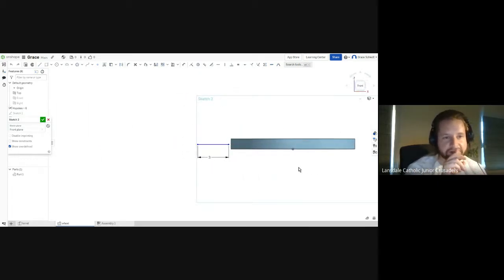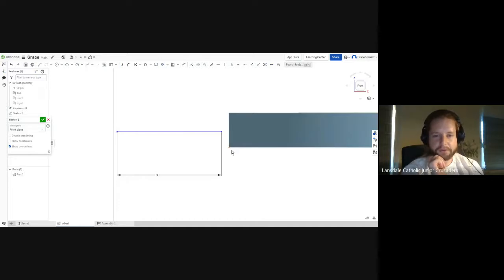So do you see how your sketch one isn't visible right now over in the left? Yeah. Yeah, click that. There you go. Now you can see that sketch. So zoom in a little bit. And now you can draw a line from that point up to the top of your part. This is going to be a construction geometry line. Like that? Yep, that works. You can also use the Q key. And then you're going to make that line vertical. So click on that line and make it vertical.